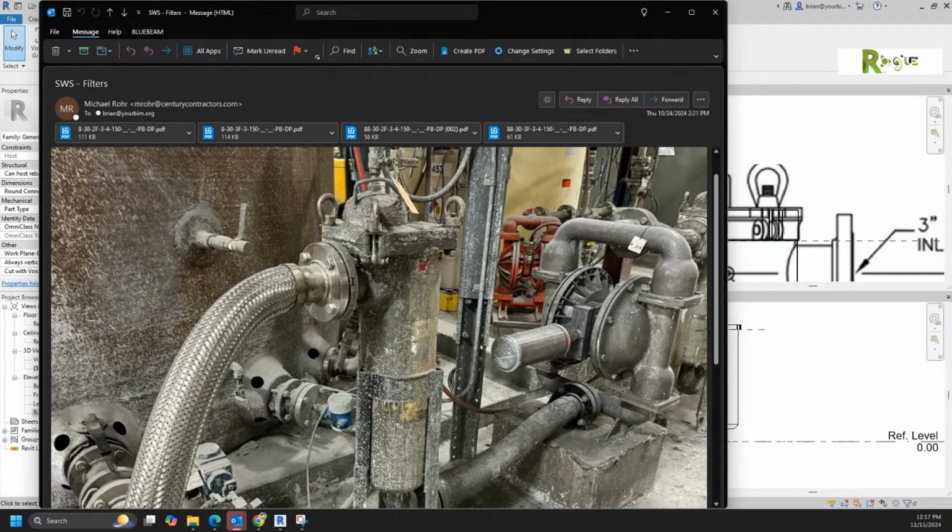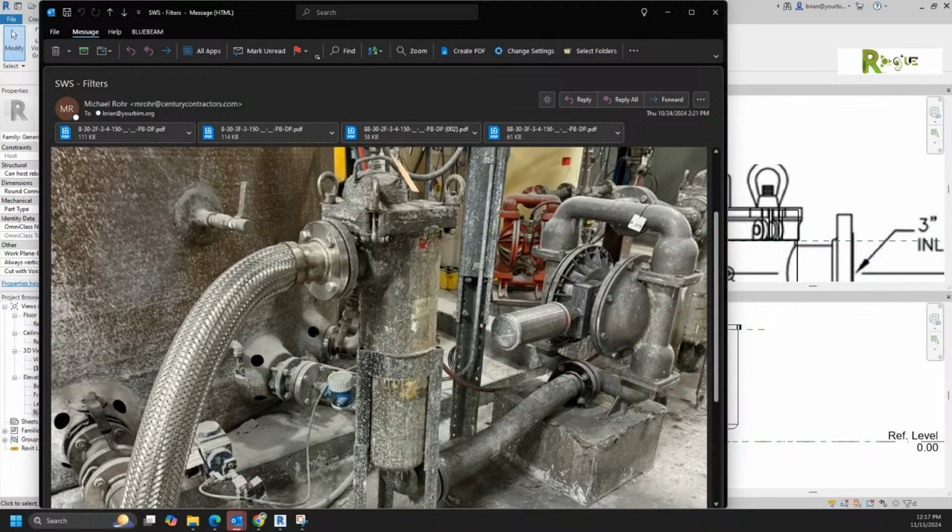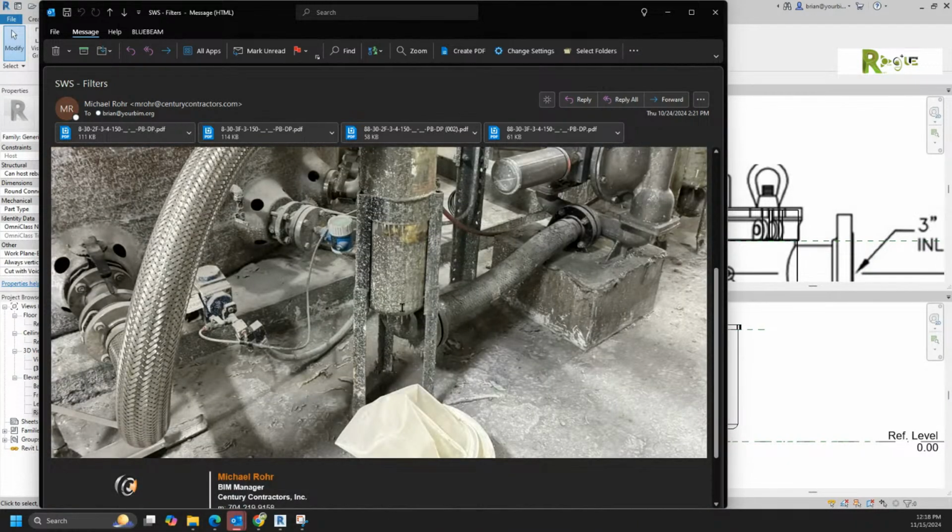Am I making that to be that diameter, or am I making that to be adjustable? You were making the legs? Yeah, the round part that clips on. Am I making that to be a part so that it's adjustable in diameter? So the only adjustment that I need is to be able to adjust the length of that guy, up and down. I'm going to need that to be an instance parameter, but I just need the top attached and the bottom attached. I don't mind throwing that parameter on there once we get it in.